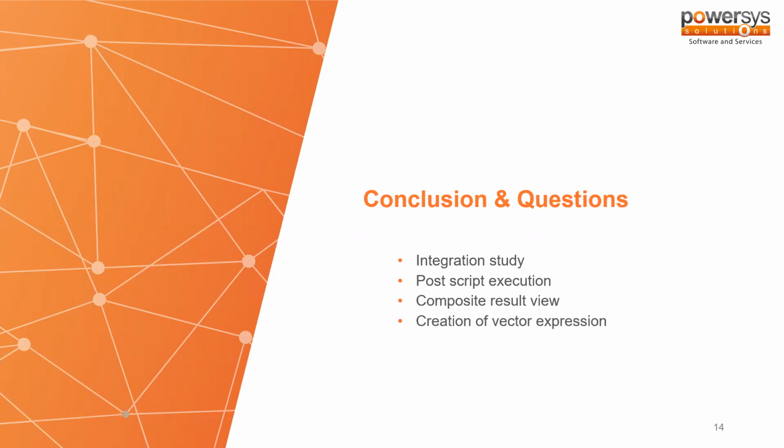But technically, if you create your own algorithm of point selection for your machine, you can still draw the efficiency map using an accuracy priority efficiency map. It's not yet implemented, but if you're savvy enough in selecting the operating points that need to be calculated for your efficiency map, you can actually do it. That would be my answer for this one.